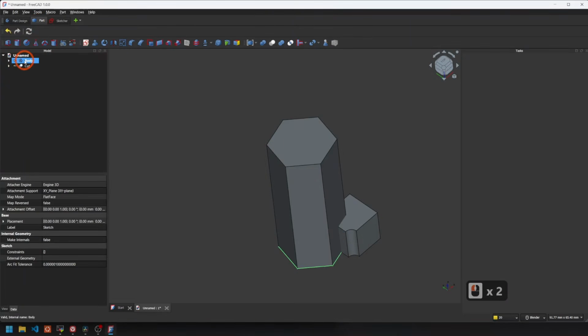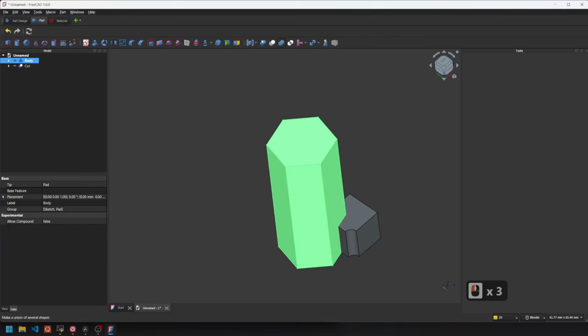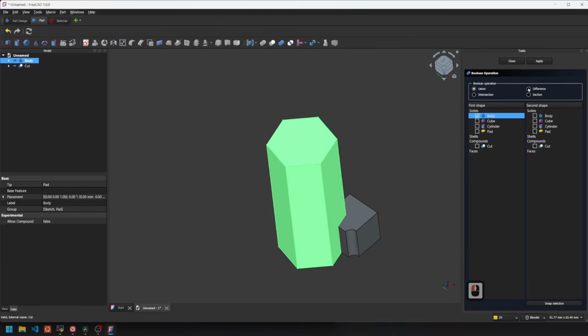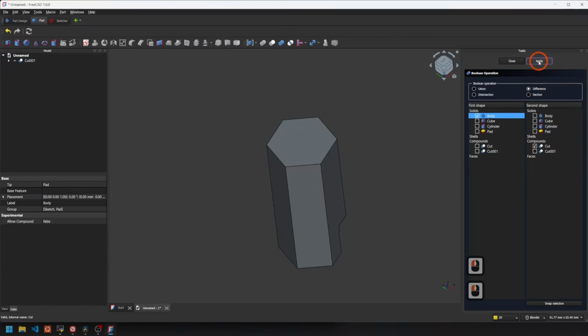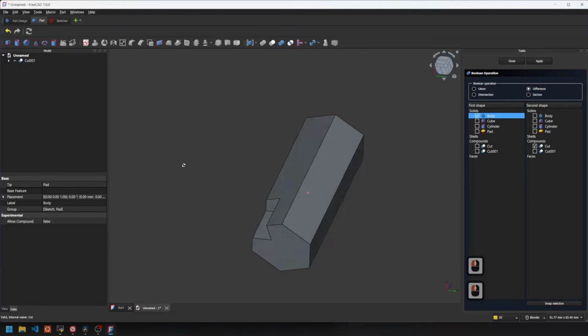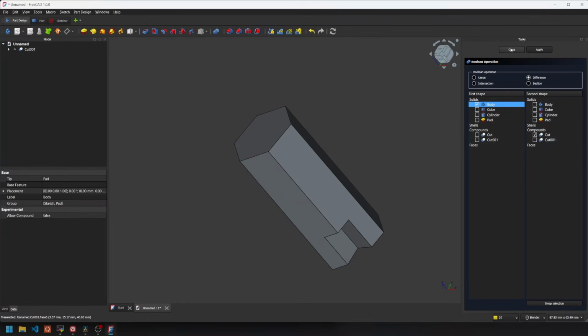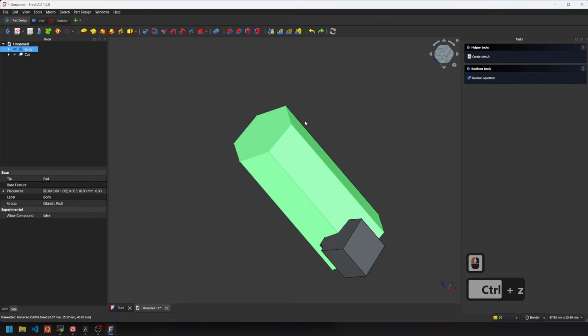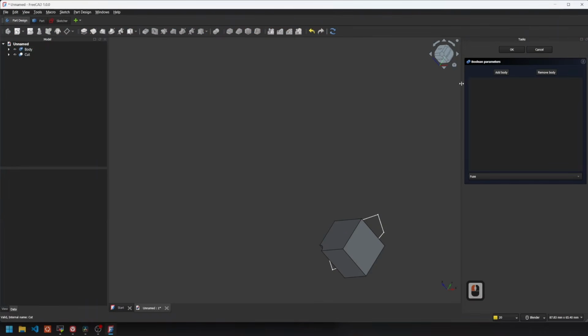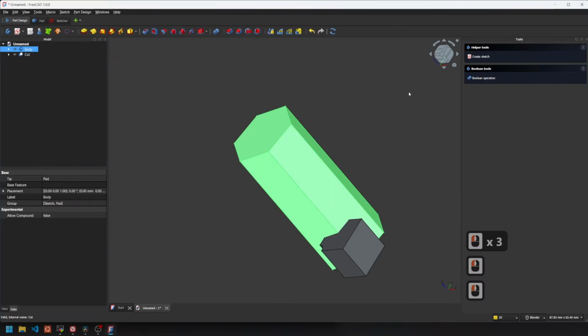And this is now our solid object. And we want to do a difference operation to it. So let's select the cut. And there we go. In the part designer, this is more complicated, but we can try to do the same in the part designer. So let's reverse it. All right, like this. And now we are in the part designer, and I'm going to select Boolean operation. There we can see the difference.